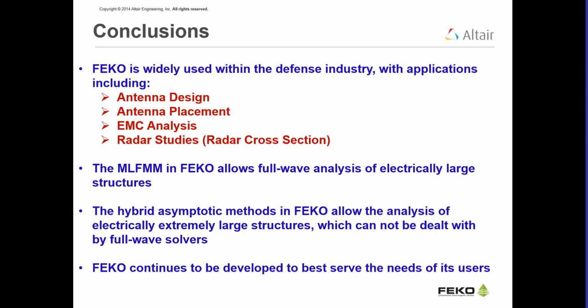And also alternatively, FEKO also gives an option for multiple configurations. That is, you create one base configuration and you can have multiple configurations that are different from the original configuration. So in those multiple configurations, for the second one you can say, use the NGF that's already done, so it can be read from the file and can be used. Those are the two questions I have here.